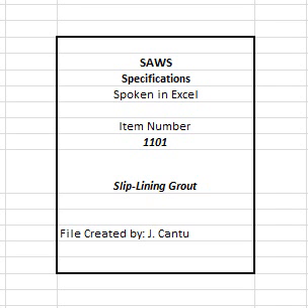E. Initial set time of the grout. F. The 24-hour and 28-day minimum grout compressive strengths. G. The grout working time, before a 15% change in density or viscosity occurs. H. The proposed grouting method and resume of successful uses on previous projects. I. The maximum injection pressures. J. Proposed grout stage volumes.